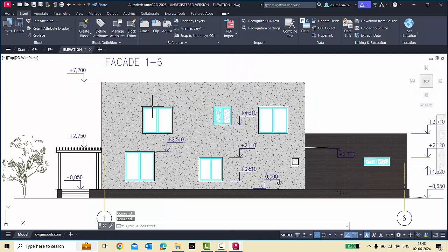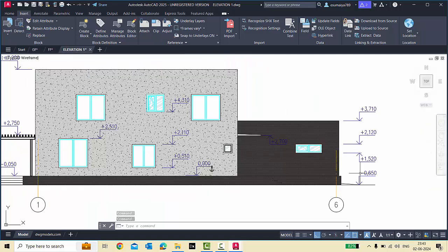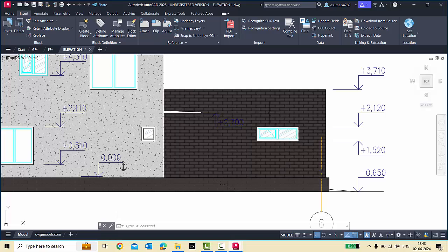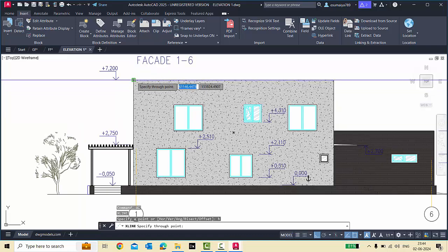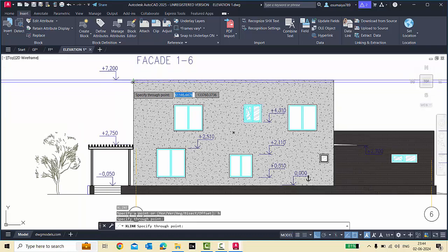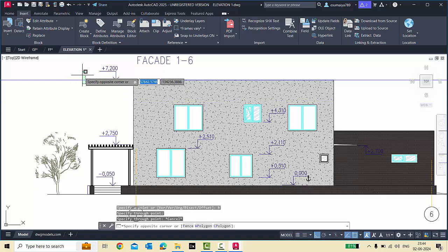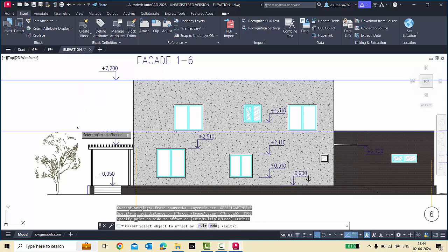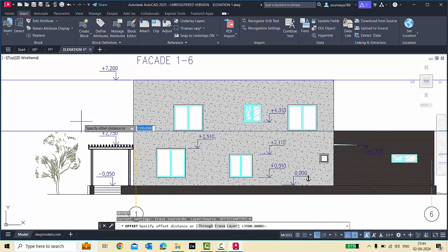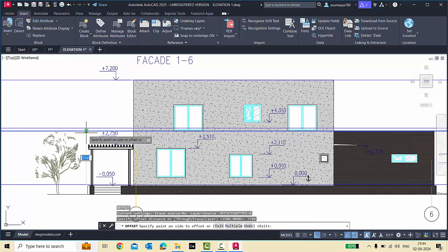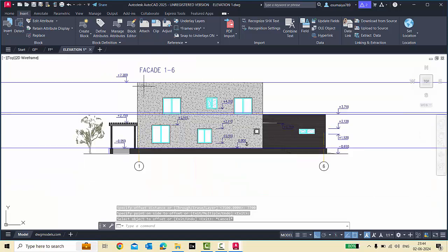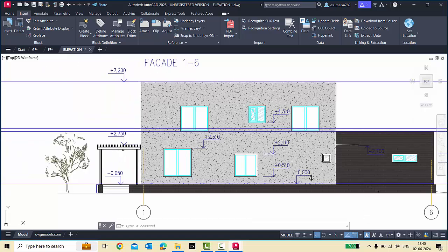When I see this elevation 1, it's a simple structure, and as I mentioned, it is a car shed. Since they haven't mentioned the height of one floor, I assume, since it's 7.2 meters, that the height of one floor will be 3.5. Let's verify that. Offset 3500. If 200 is the floor thickness, it will be here, and again offset 3700. Usually the height of your story will be mentioned, so these heights are very important for us.